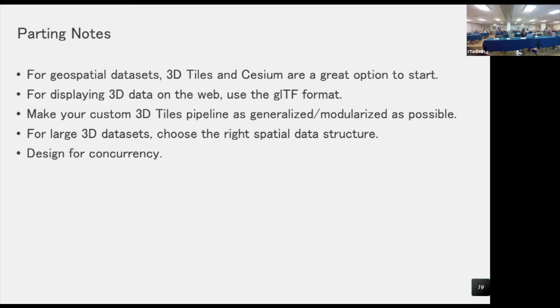All right, here's another question. At the scale of the problem you're working on, is the curvature of the Earth a factor, and do 3D tiles accommodate that? Yeah, so 3D tiles is designed for use with a web engine, and it's an open spec. So this could be implemented in something like Unity and otherwise too. But when you're working with this data, it's really important to understand the difference between a Cartesian coordinate, which is your XYZ, and your cartographic, which are your lat long altitude.